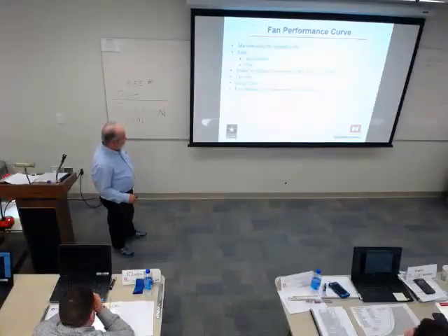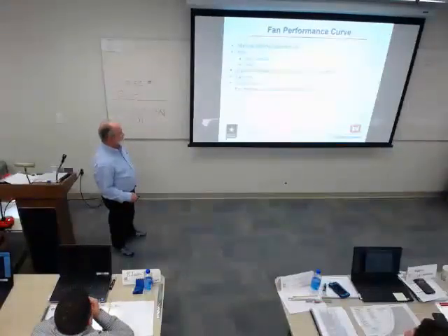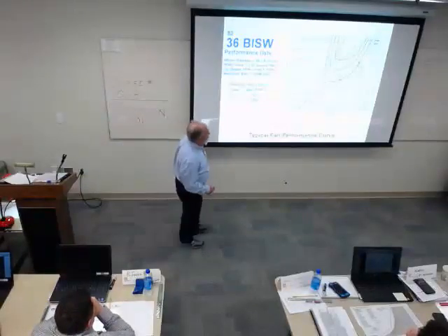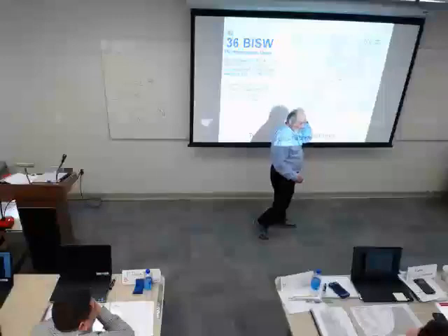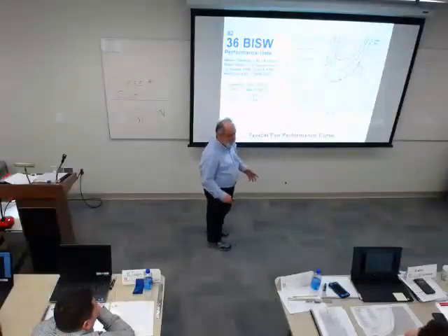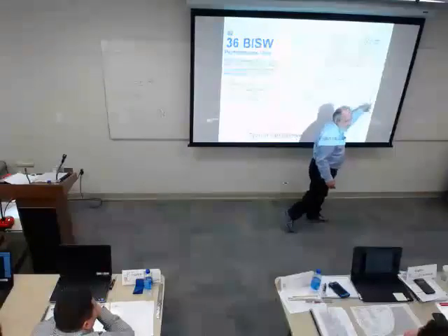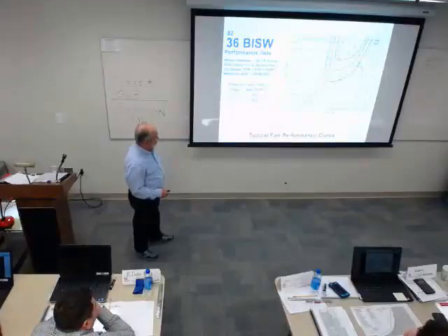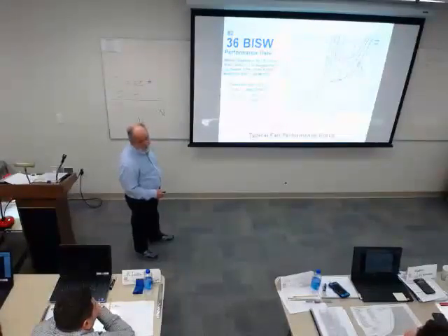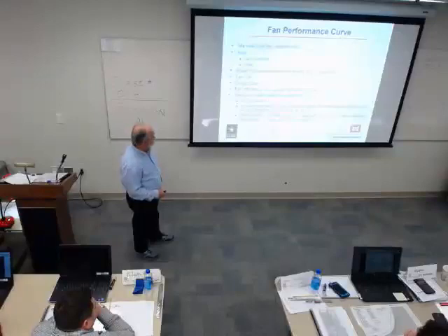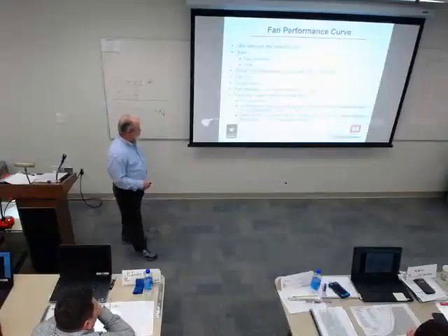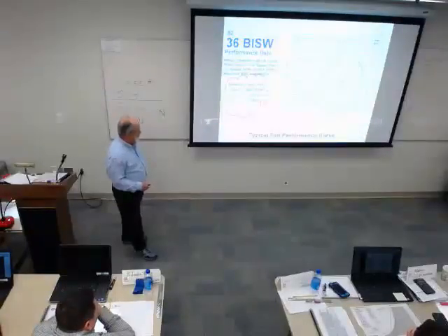So, okay, we have the brake horsepower, the fan RPM, the surge curve, and the fan efficiency is not always shown. It's nice when they do it like that. Often, if they don't have those plotted on there, they'll have some other way of letting you know. Sometimes they'll have efficiency curves plotted with a different range over here for efficiency. But this, I like seeing like this. It's really handy, as you can see immediately what you're doing. All right, so let's see here. Go through the surge curve, pressure classes. That's the thing we talked about there.